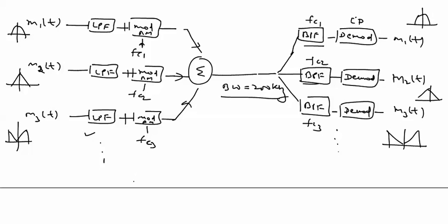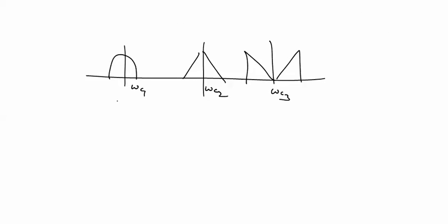The composite diagram can be constructed in this way. The complete channel bandwidth is occupied by three message signals, in our example. If the first signal is centered at omega c1, the second and third likewise, they travel in the channel in this way. Between the message signals there is some spectral bandwidth gap. This is known as the guard band.